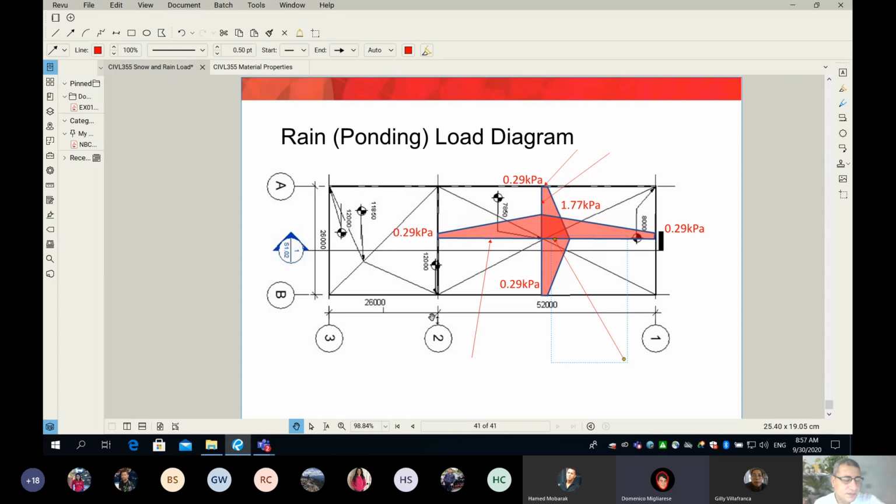Taher, go ahead. Like this roof looks like it's designed to have that drainage go through the middle, through the building, correct? Yes. So then wouldn't putting the scuppers on the side be somewhat useless? Those are basically a safety mechanism in case it rains a stupid amount in that day?